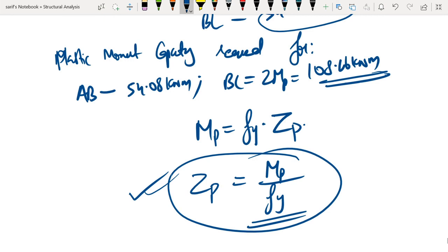So what we have done in this session is, we have tried to calculate the plastic moment capacity of continuous beams. The idea is that we consider each span, and for each span we calculate the plastic moment capacity required. If a particular span has multiple mechanisms possible, then we have to explore all the possible mechanisms. After considering all the mechanisms for each span of the continuous beam, we compare and take the largest value of MP required and design each span for that.